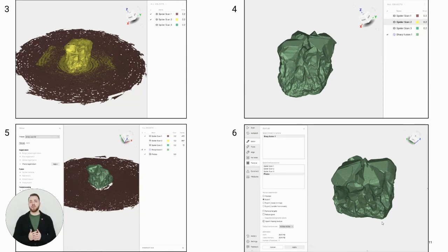That's actually the trickiest part of the whole technique. When doing our first non-sprayed scan, we need to gather enough information about this scene so that this scan can be successfully registered with the sprayed one. If this checkbox is checked, the rest will fall into place very easily. So as we have connected the scans, we use the sprayed one for creating a fusion. Having done that, it's time to run photo registration with a pack of imported pictures. Yeah, no, the pack of imported pictures, fusion, and the first scan. Remember? The first one, the non-textured one.